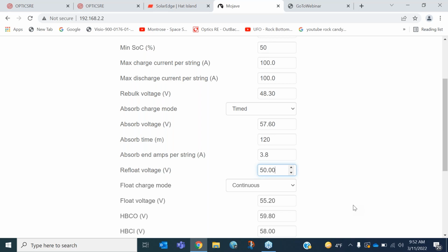You can't take what Lonus's system is and assume it's something that you're going to be installing, because for the foreseeable future, we're selling it as the ESS. So it will come with the battery. And I know this was discussed on the first presentation: the battery is a 15 kilowatt hour. It's actually 14.8, which gives it about 12 kilowatt hours of usable power at 80% depth of discharge.